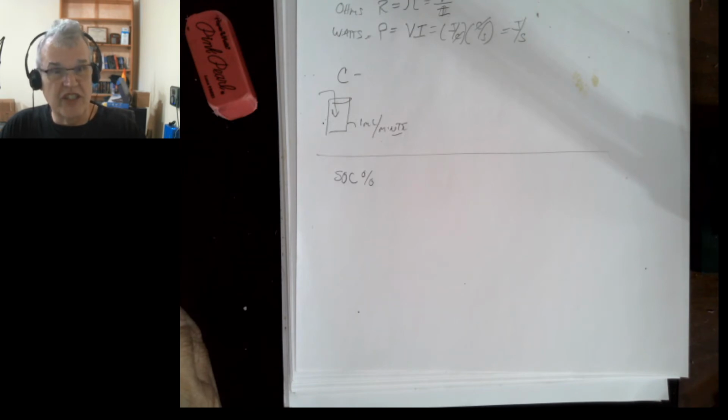Is it fully charged? Is it halfway charged? Where is it between its cutoff voltage and its maximum voltage, which is also its complete capacity and 0 capacity? Because once you get to the cutoff voltage, you consider that there's no more useful capacity left in the battery. Depth of discharge, it's another term that's also used. It's kind of the reciprocal of the state of charge, right? Depth of discharge is how far do you discharge it?